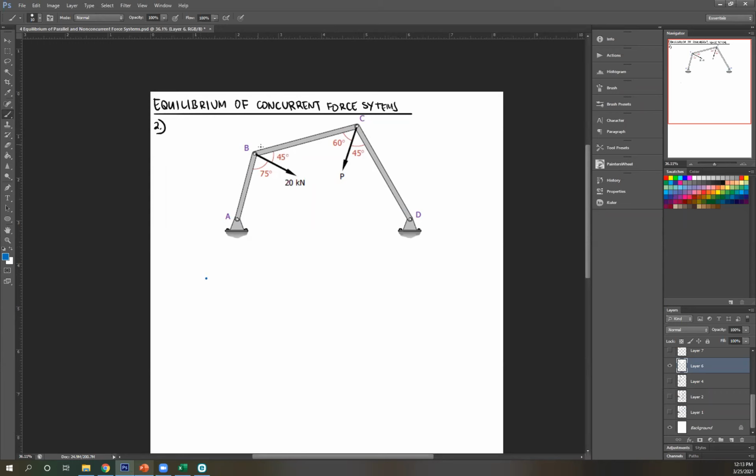So just follow the lines, the orientation, okay? And then usually for pin connection, reaction would be to the point, okay? So I'm gonna draw this. And this is my point B, so force AB is directed to it. So that's why this is my arrowhead. And again, this is your force AB.